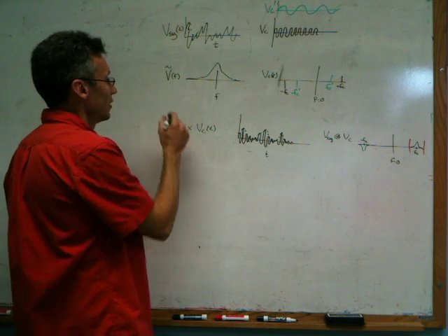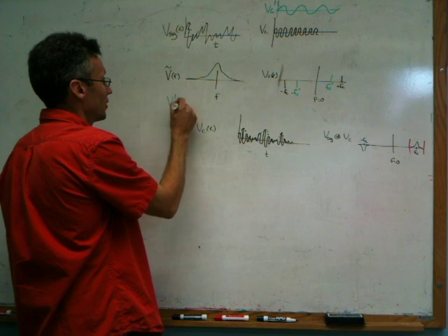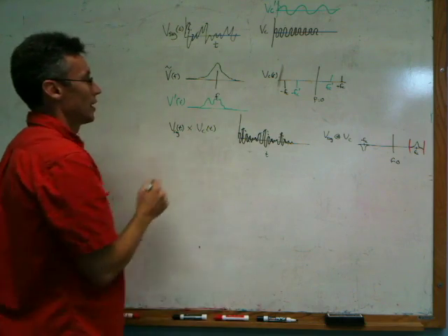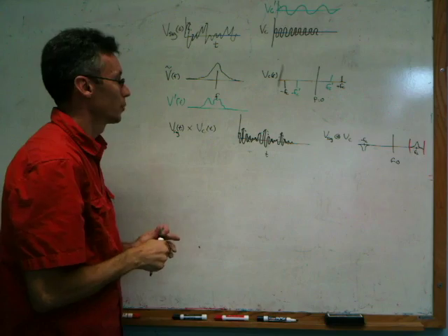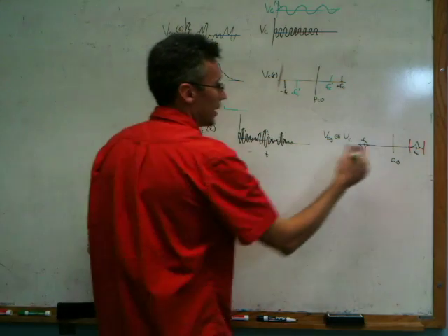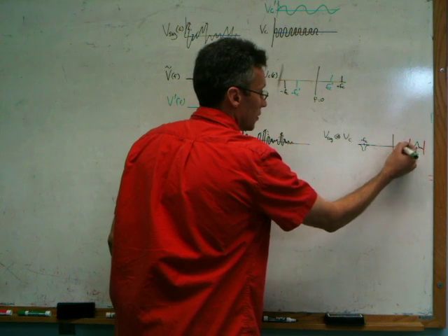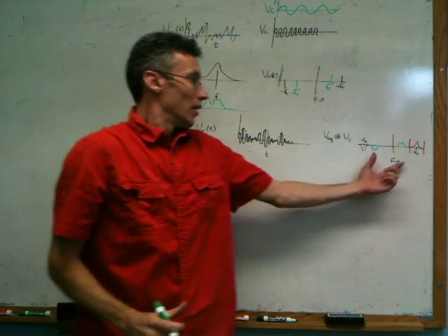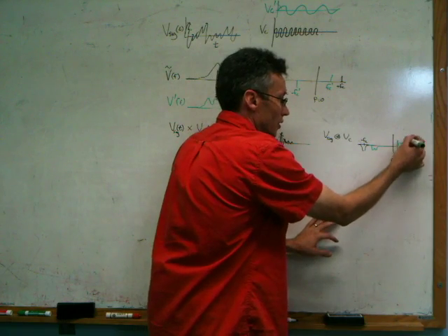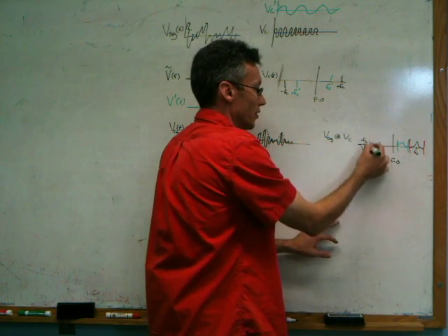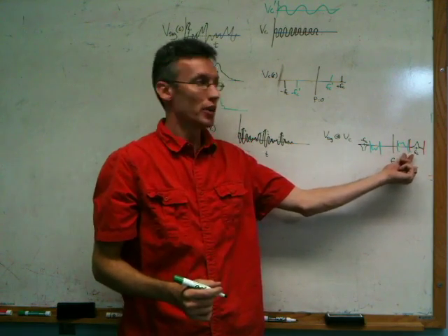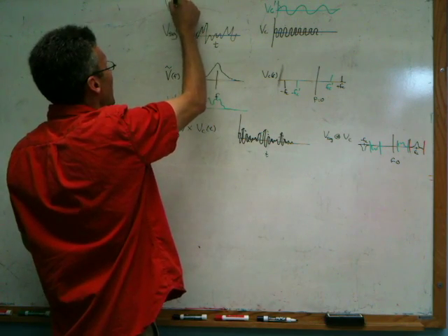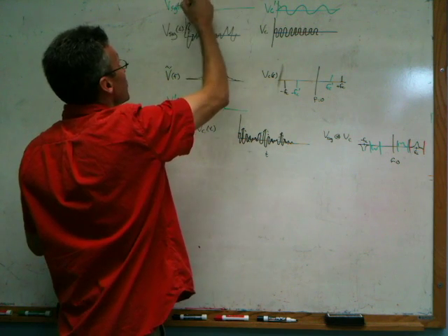And therefore, if I have a different signal, maybe a different radio station that has a slightly different spectrum, that gets shifted by a different amount and sits over here at a different center frequency than my original signal. So I've essentially now encoded two different signals. So I can start with the time domain representation of these two different signals.